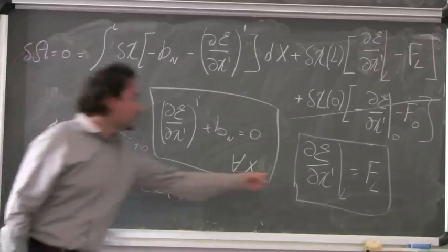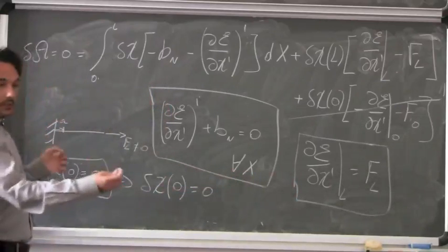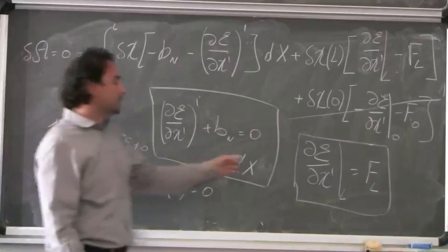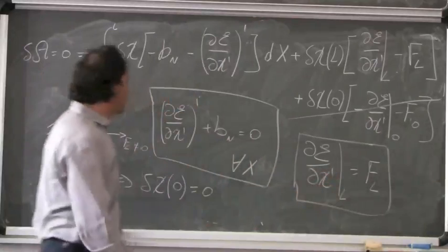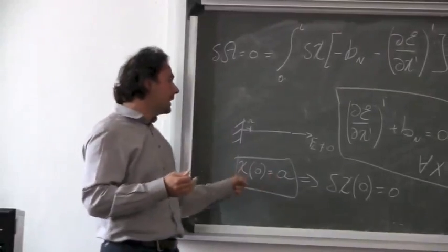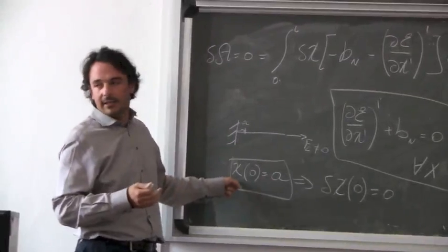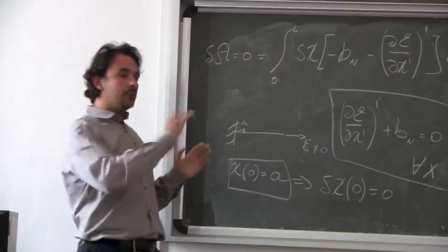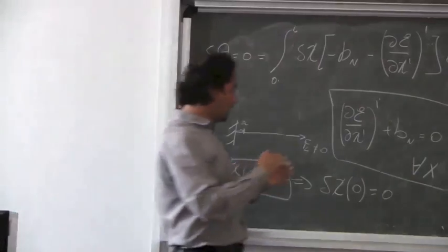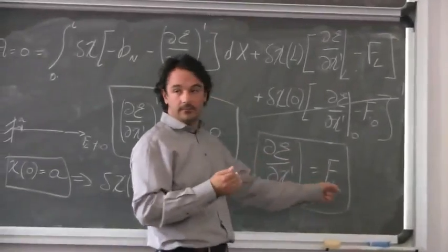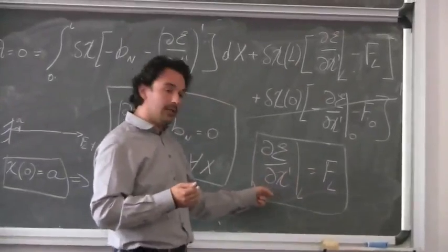So we have two boundary conditions at the two borders. This condition can be kinematically defined or dynamically defined. If you impose some constraint on your displacement, the boundary condition comes directly from your restriction. If you don't impose anything on the kinematics, the boundary conditions that you have to impose are calculated. It is this one, exactly this one.